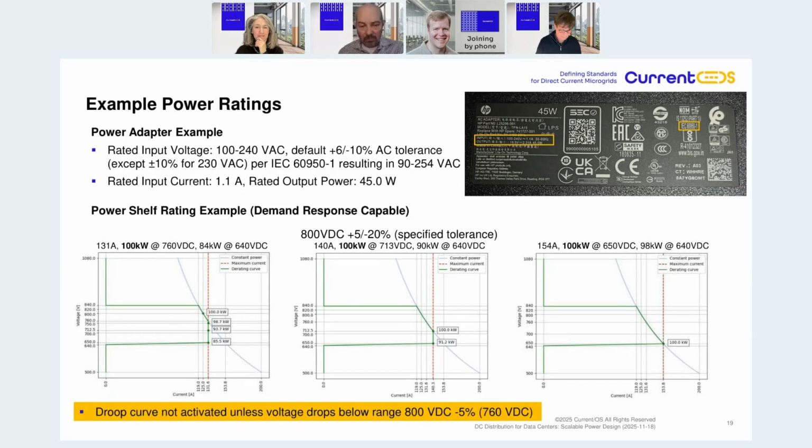I mentioned on a previous slide, but didn't highlight in the text, that, for example, preferred voltages within China are, say, plus minus 375 or plus minus 750. So if you wanted to support that fully, you can see here that by increasing the current rating of the component by 9 amps from 131 to 140, you would still be able to support full power for that particular voltage.